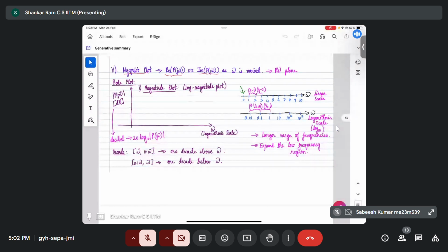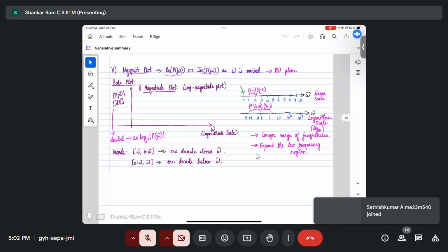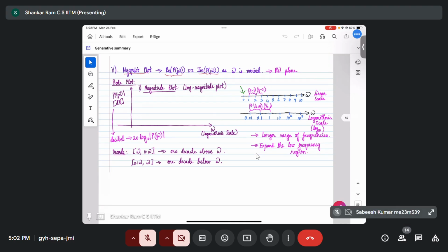So if you recollect, we were looking at frequency response, which is the response of stable LTI systems to sinusoidal inputs, and we were interested in figuring out what the steady state response of this class of systems would be. I know because it's practically useful, right? Because we can give sinusoidal inputs in practice, measure the output, and try to figure out the system transfer function from those output measurements. Okay, so that is where there's a practical application.